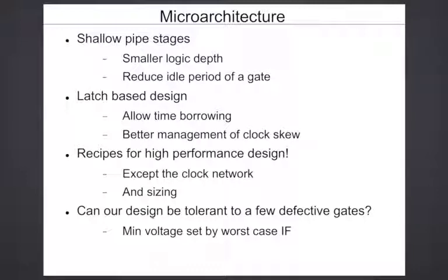And remember, this has to also fit into the flow. Any digital design methodology has to fit into the digital flow. Is this something where the RTL designer doesn't worry about it, but as a backend step, the system figures out and does the redundancy? Just like what we do for testing now. Testing is something where all the circuitry for test is inserted in the backend. The designer doesn't really care about testing. They do their design. So something similar will probably have to be done: a methodology which will allow you to take a design and then make it robust by putting in redundancy and so on.